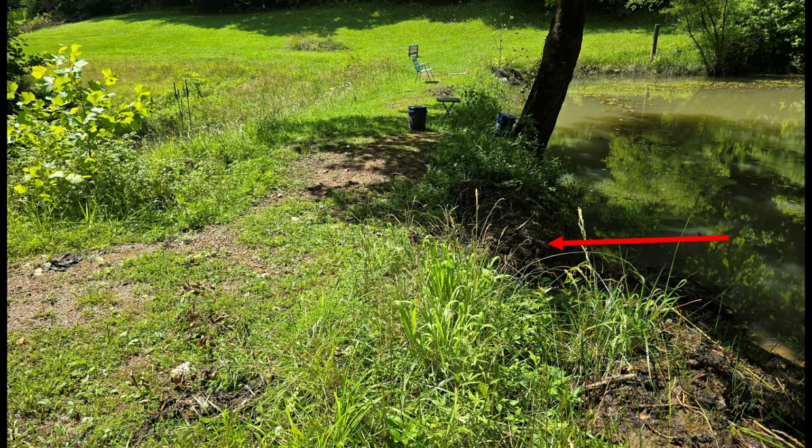I recommended filling the entrance to the third and the shortest section of pipe that was buried in the dam. I wanted to fill this with soil to prevent water from flowing through or around it. I was concerned that water flowing in the old pipe could wash out the dam because it was short and rusted.